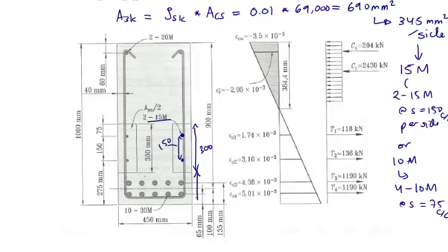This thing here, if you look at the previous figure, is just 2 times H minus D. So that's just 2 times 100, equal to 200. So that's how you know where you start this area over here. And then you would place those rebar in that area. So that's the example on skin reinforcement.